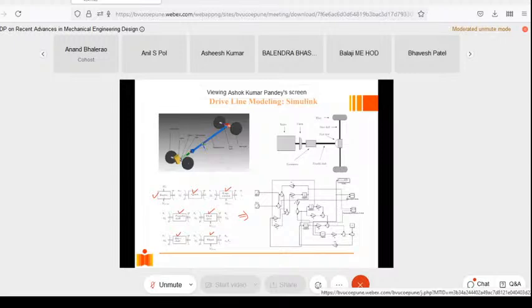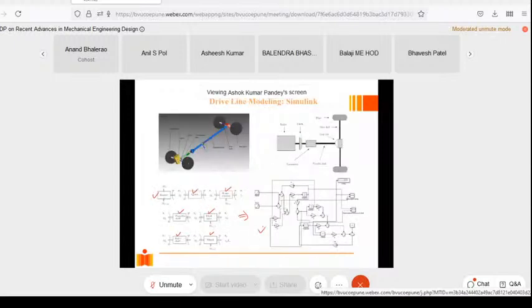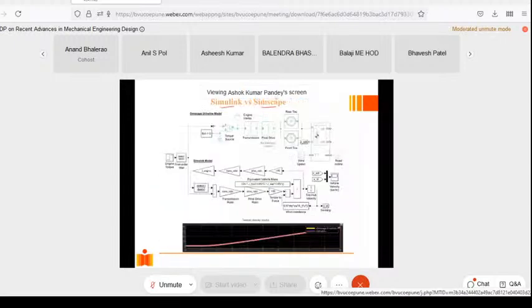So in MATLAB, basically there are two types of systems available. One is your Simulink, another one is Simscape, which is also called the physical model. Okay. So this is your Simulink model. Okay, it appears like this. But Simscape will have physical blocks like this, and you can define the data straight away. These are the wheels, front wheel, rear wheel. This is the car body, wind speed, and engine input you can give.